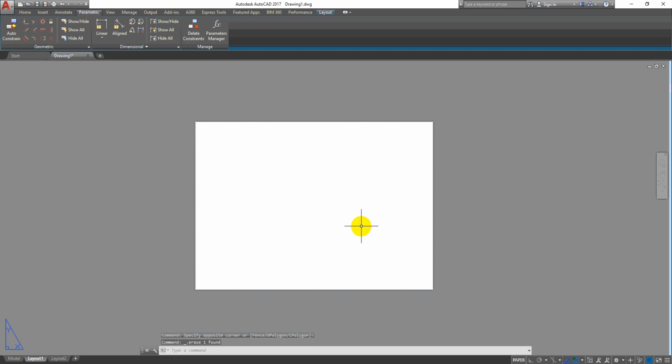So this is very important when it comes to sheet set manager, because you will be having a template, and in that template you would have already set up the desired layout. Okay, suppose you want to have your drawing on A2 size. All the drawings are going to be on A2 size. In that case, you will be using that particular template. In that template, you would have set A2 as your drawing sheet size.